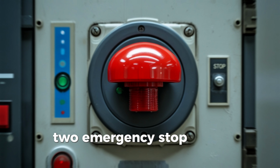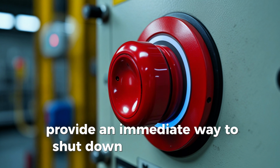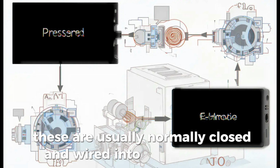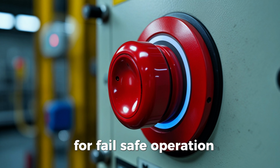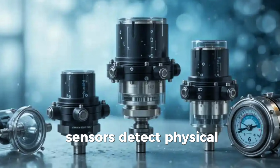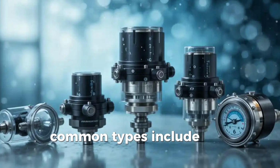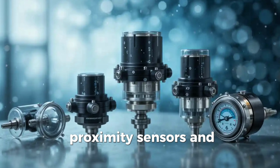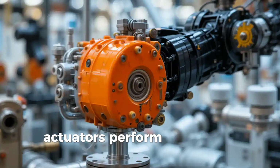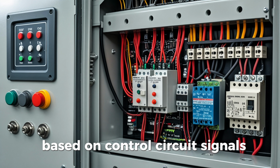6. Emergency stop, e-stop, systems. E-stop buttons provide an immediate way to shut down machinery in an emergency. These are usually normally closed and wired into the stop circuit for fail-safe operation. 7. Sensors and actuators. Sensors detect physical parameters like position, temperature, or pressure. Common types include limit switches, proximity sensors, and temperature sensors. Actuators perform actions like opening a valve or moving a part based on control circuit signals.